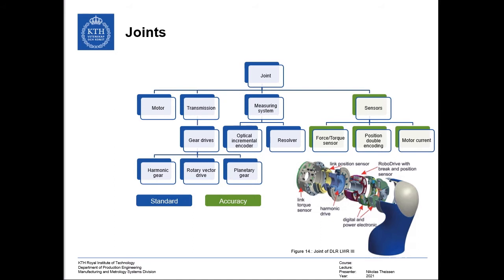The disadvantages of harmonic drives are elastic wind-up, that is, the torsional stiffness leads to a distortion which has a similar effect as backlash, and their lower stiffness, while the other gears usually feature a low stiffness at zero torque due to their play.